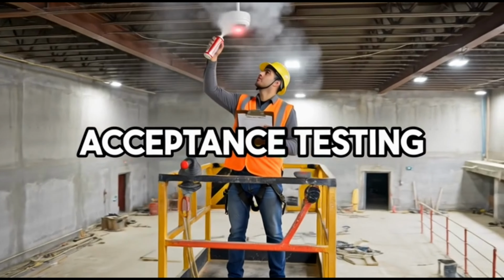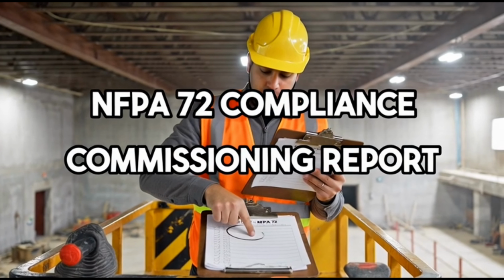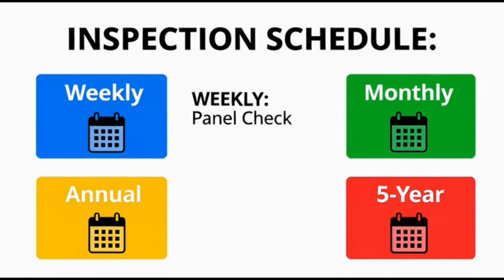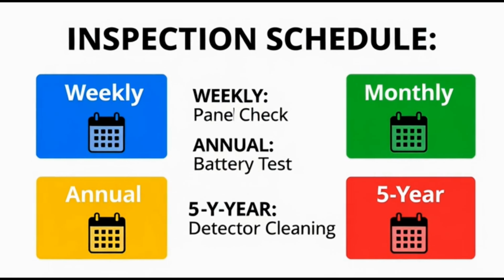Acceptance testing proves the system works. You must test 100% of devices per NFPA. Reliability requires ongoing care. Perform weekly panel checks. Check batteries annually. And remember, smoke detectors need internal cleaning every 5 years.